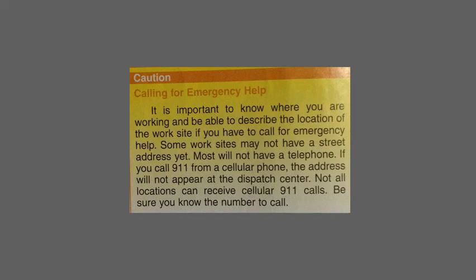A first step in protecting yourself is to wear clothing that is made of flame-resistant fabrics while you're working on electrical equipment. Treating a burn involves removing the source of the heat and calling for medical help. Burns caused by electrical shock or arc flash are usually too severe to be treated by anyone other than a doctor or paramedic.